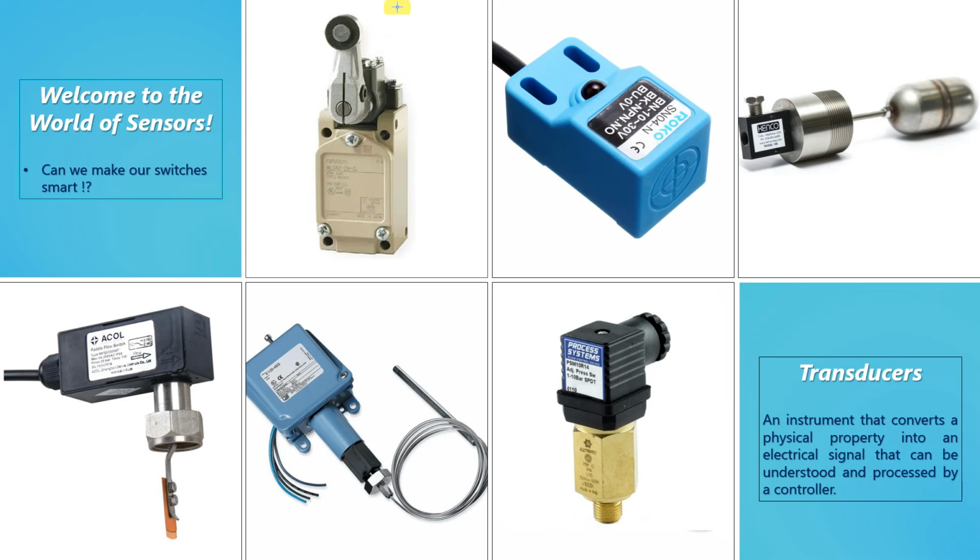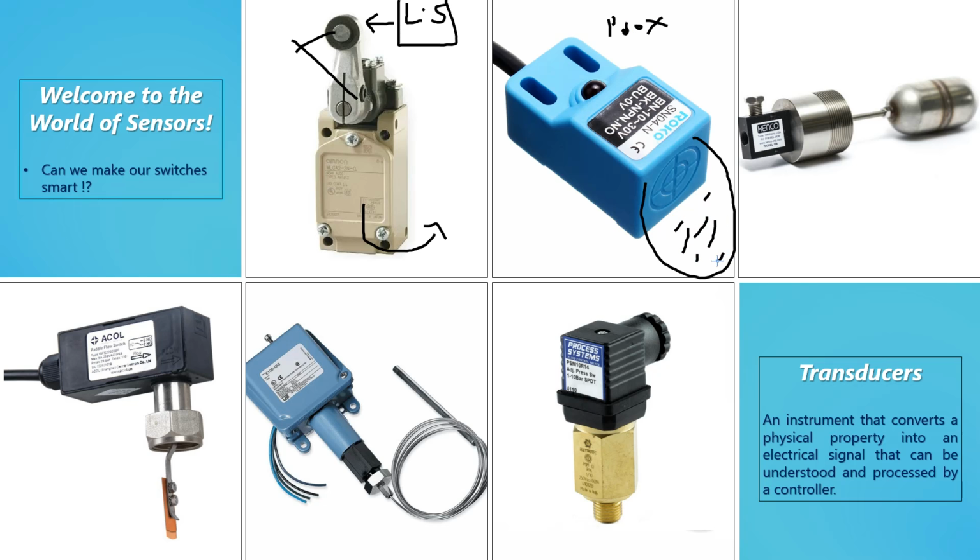Let me explain. Now, here in the first picture, we have something known as a limit switch, right? When an object touches or makes contact with the sensing part, it generates an electrical signal which indicates that indeed an object is present and it has made contact. In the second picture, we have what's known as a proximity switch. It generates a field of detection around its sensing plate. There are numerous technologies that are able to achieve that, and we are going to discuss this later in the presentation. So when an object enters this field of detection, the output signal generates and it is taken to the controller.